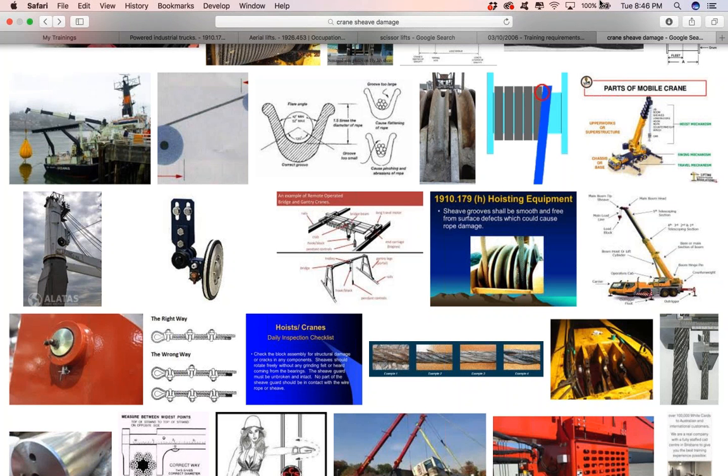And basically, what are we talking about, right? Operation of motorized equipment requires concentration by the operator, right? Can't have any distractions that could wind up in any type of significant injuries, illnesses, or fatalities. At all times, the operator's got to have a clear view of the site or the equipment. Like we said, if not, they're going to have a signal person or a spotter, right? And they're going to have to maintain a minimum of one type of communication with the signal person, either audio, whether it's voice, radio, and/or visual. But at least one form of communication is going to have to be maintained.